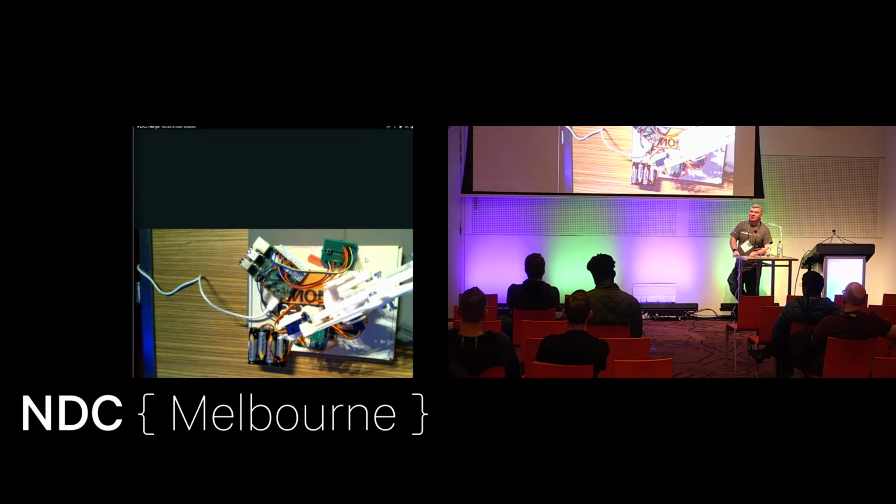If you want to do C# on microcontrollers, you can. You can use something called the .NET Nano framework, which folks like Jose Simoes have created, and that's C# for microcontrollers. And it works really well. So there's always a balance. It just depends on how much processing power you need. If you want to do AI at the edge and you're not buying a specific AI microcontroller, then this is going to work really well. If you're flashing an LED and reading a button and things like that, just use an Arduino. It's really going to be up to the particular project you're going to be working on.